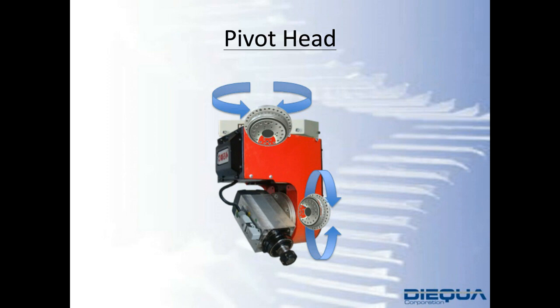If we were to simply connect to a hollow keyed output shaft, repetition might oblong or wobble out that key. If you were to put a shrink disc on there, you'd have to have higher quality tolerancing on the components that you're mounting with. We could go into further detail, but just to give you a visual of how robot flanges help you provide a more compact solution.